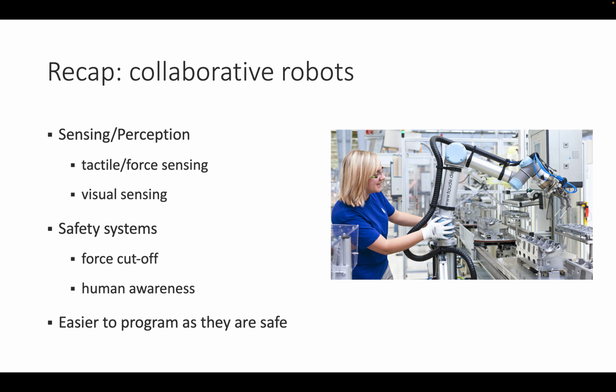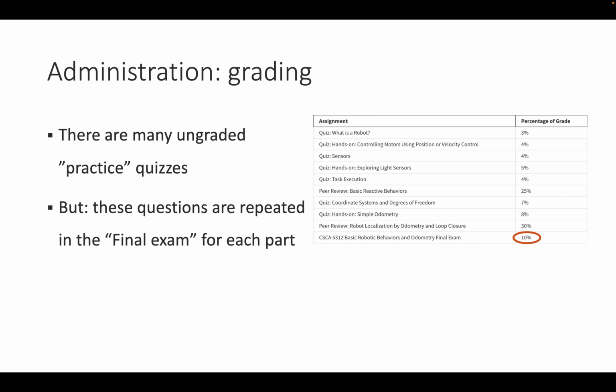The really big advantage of collaborative robots in practice is that they are much easier to program for humans, as they are safe, so the human can be together with the robot, move it around, see immediately what it does wrong, understand what needs to be done and fix that. Therefore, they work much closer in a closed loop with the robot during programming. Conversely, robots are often then replaced with cheaper and simpler industrial robots that can move faster once they have been demonstrated in a certain environment.